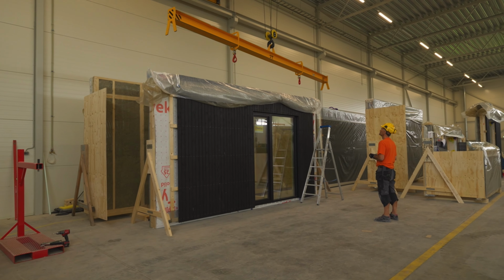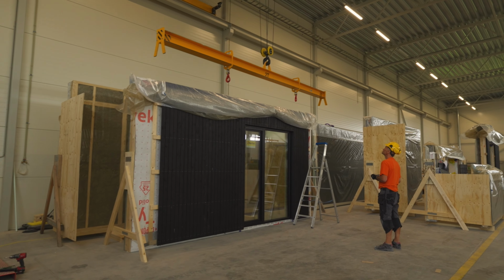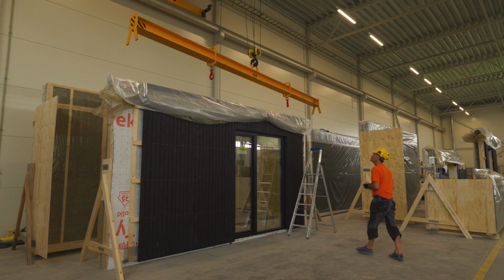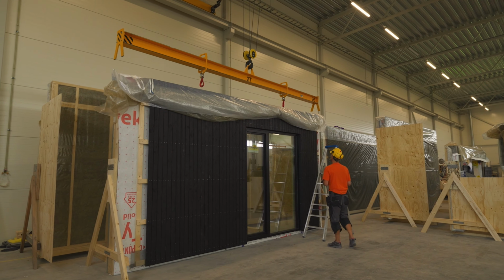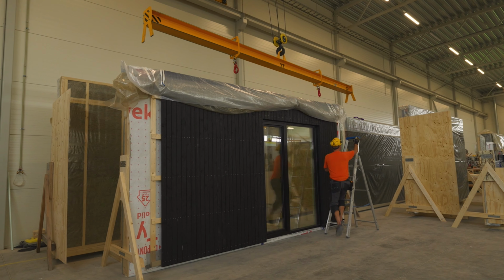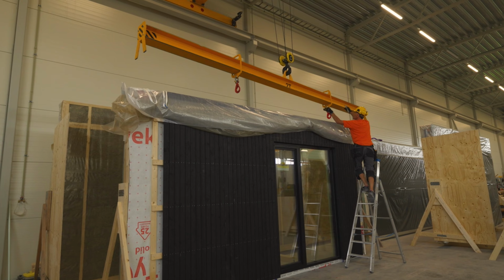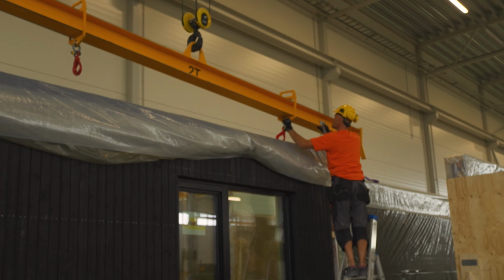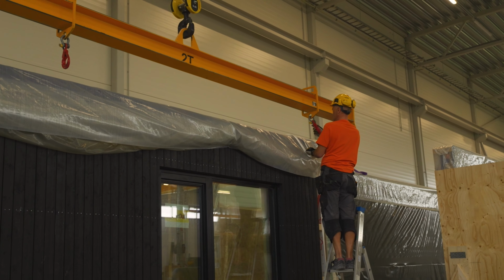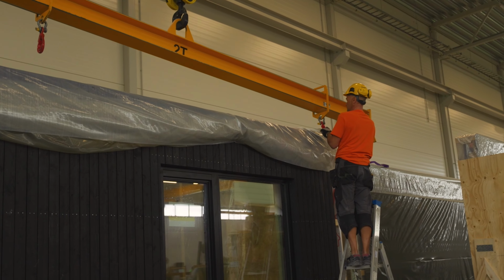When lifting elements, a spreader beam is usually used. A spreader beam is a metal structure used as an aid in lifting operations to ensure that the lifting straps attached to the frame are straight and do not deform the structure during lifting. It is crucial to strictly adhere to all safety requirements during lifting operations.